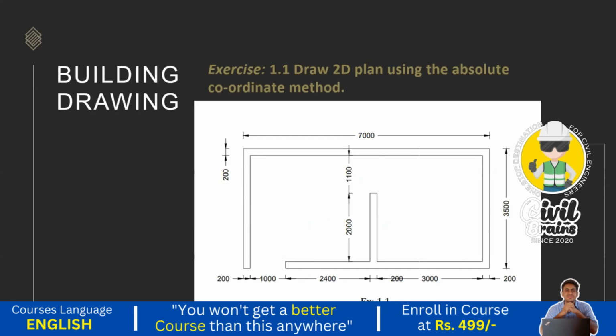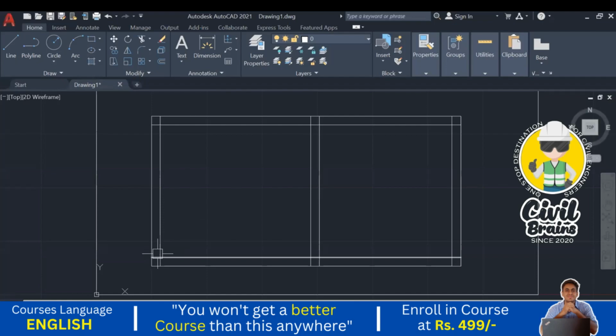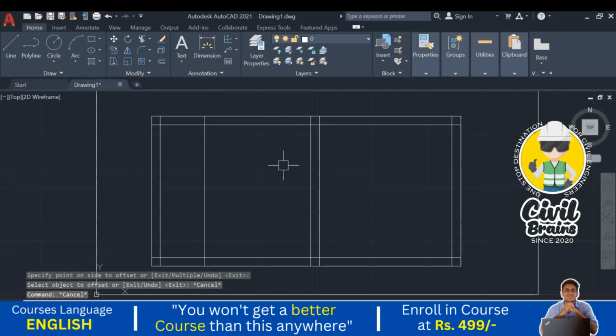In other plans, it will be mentioned whether we need to provide an opening or a door. What is the difference between a door and an opening? Okay, I go here, need to provide the opening. Again I go to the offset command. The offset is 1000. Press enter. I take offset 1000, and for this opening or door offset, I go to the offset command again, that is 1100.